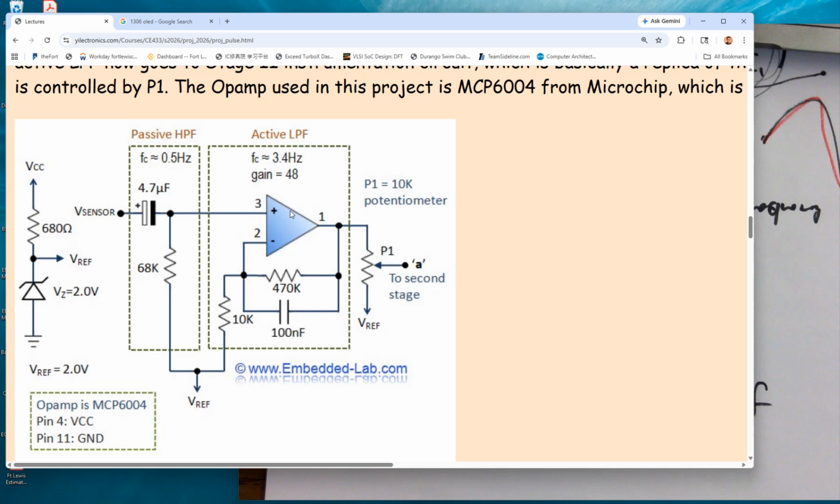So I was searching for 1 volt op amps, and I didn't see any. So the lowest is about 1.8 volts that I can see for the VCC. There must be 1 volt op amps, but probably it's very expensive. But 1.8 volts is a VCC this specific op amp can take as a minimum.